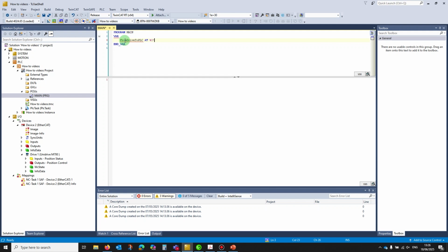Now the reason why we put an asterisk on the end is that it tells the system, look, I want it to be mapped into my PLC I registers, but you can decide which actual memory location is assigned. I don't care what it is as long as it's in that area so I can link to it. If you assign it in that way, you'll never have any problems with more than one thing mapping to the same area in memory. It just sorts it out itself, which is how I would recommend you do it. And then we're going to make that of data type DINT, because we just worked out just before that 2021 and 2022 are DINT data type.